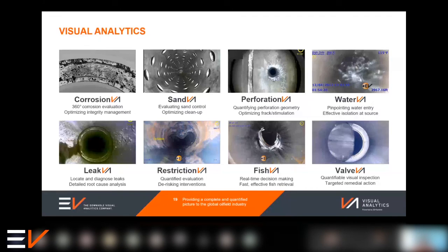But we do have camera systems that run on umbilicals, either on drill pipe or just on tugger lines, for example, with downwards and sideways viewing systems. So adapting one of those to suit your needs may be possible. It really just depends on what size annuli you have and how you want to get that access.